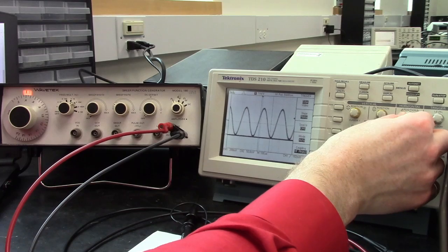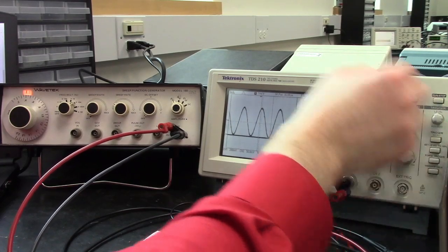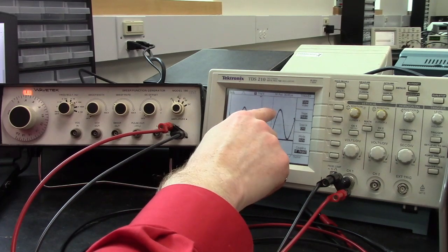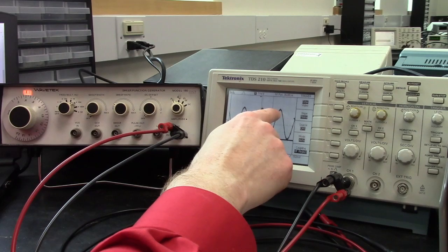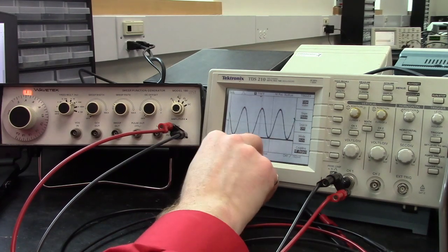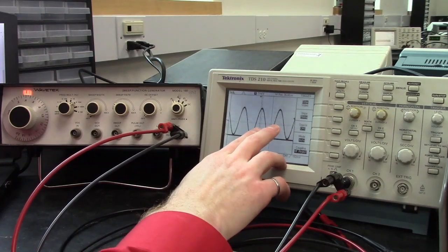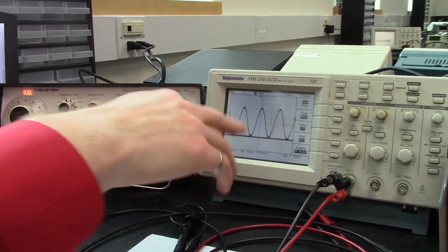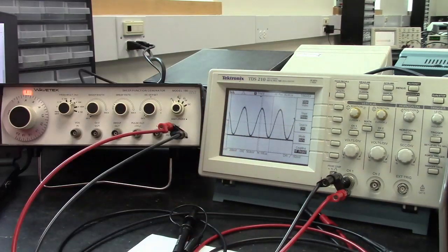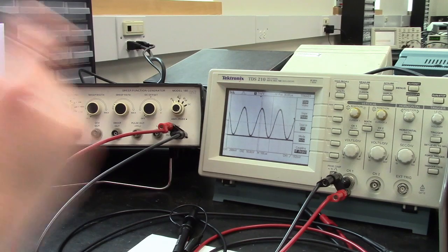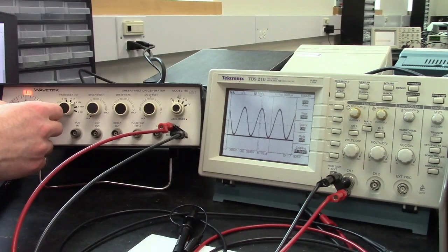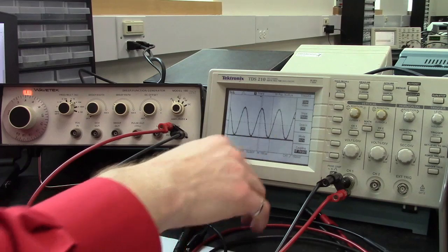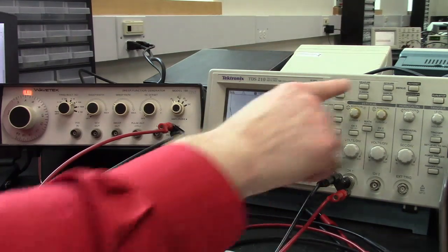So we can adjust the horizontal position here to get that to about the center and count the divisions. So this full wave looks like it takes 1 division, 2 divisions, and maybe around 2.8 for a full cycle. So that means that we're at roughly 280 microseconds for a full wave. So that tells us that we're probably not at exactly the 4 kilohertz that we are expecting. A better way than just using this setting to set the frequency and counting divisions to see what the frequency is, is to use the measure menu up at the top.